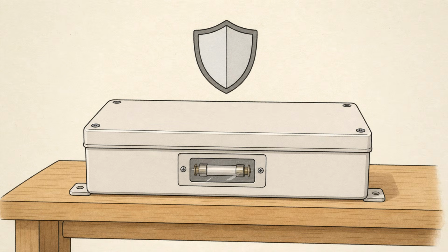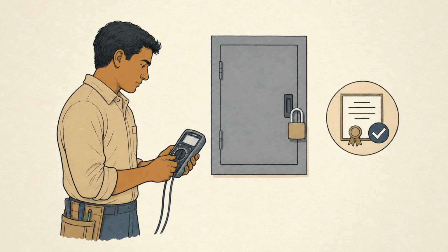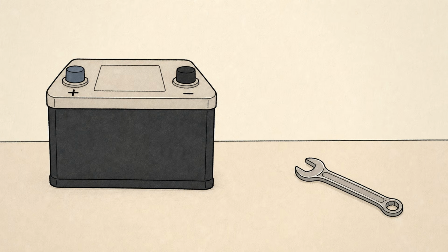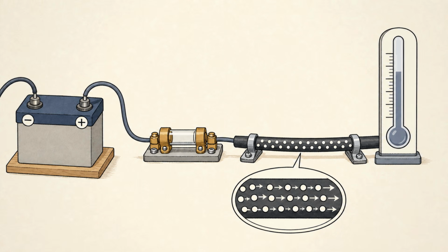Basic electricity also teaches safety. Never touch exposed conductors in a live circuit. Never work on mains wiring unless trained and authorized. Never short the terminals of a battery. Never use a power supply, wire, or connector beyond its rating. Even low-voltage systems can become dangerous if they can supply high current.